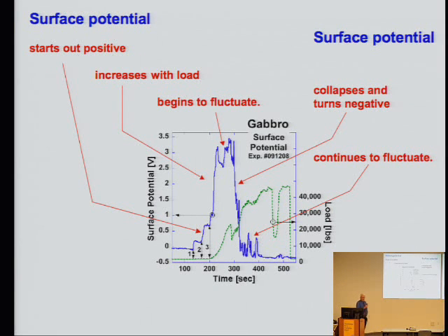Now look what we see. Mind you, these are electrostatic measurements, so we measure DC voltages, and they are exceedingly delicate. You have to keep away. You even have to hold your breath, even walking nearby. If it's not sitting in a Faraday cage, if it's sitting in the open and somebody walks by on the floor, just the charge that we build up on our bodies would have an effect on these measurements. So we have to be very careful trying to minimize these effects.